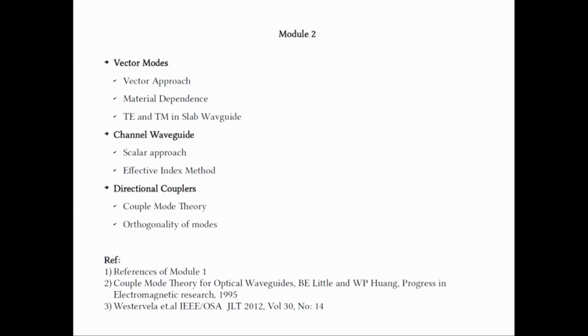We apply this to the wave equation to obtain the variation of the fields. The coefficients A and B, or U and B, whatever we considered, are treated as variables with respect to Z and represent the power exchange process. After substituting the superposition into the scalar wave equation, we obtained a set of differential equations for A and B, which are called the coupling equations.